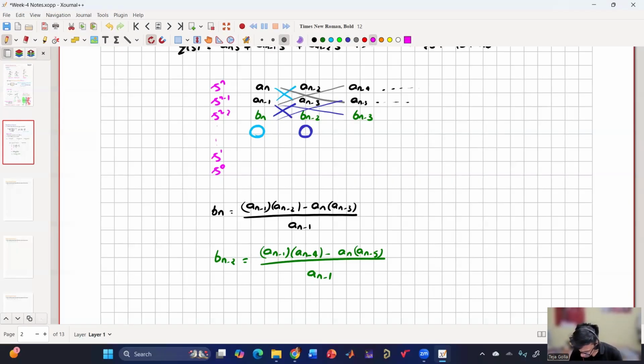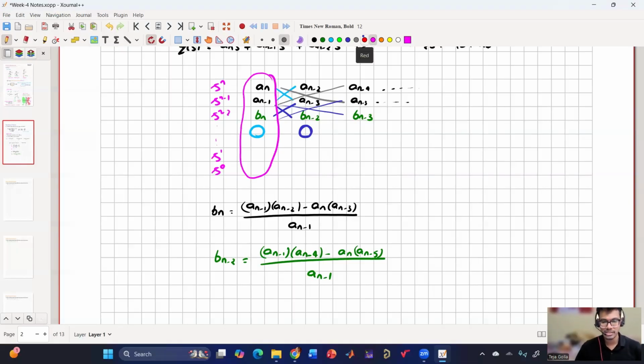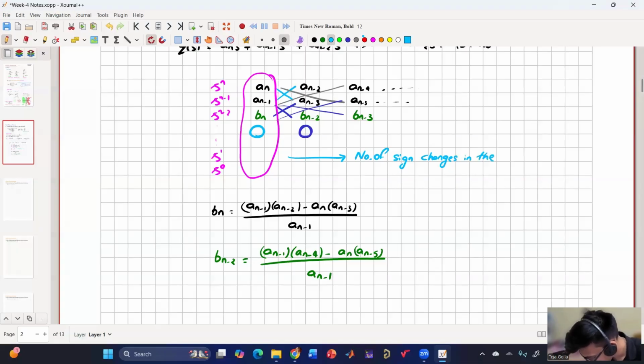And then we are interested in the first row. If all the elements in the first column are positive, then we can say all the poles are on the LHP side. The number of sign changes, from positive to negative and negative to positive, say two sign changes, in the first column is equal to the number of poles in the RHP. If there are no sign changes, then there are no poles in the RHP.